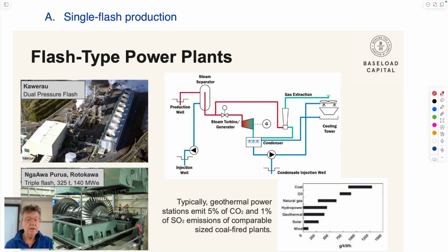It would run hot water that would flash to steam, that would turn these turbine blades, and on the back end of this would be a generator to be able to take this rotation and generate electricity from it. Then the excess water would be taken out. It might be run through a binary plant, or it might just be run through a condenser to be able to condense it and turn it from steam into water and then repump it underground.